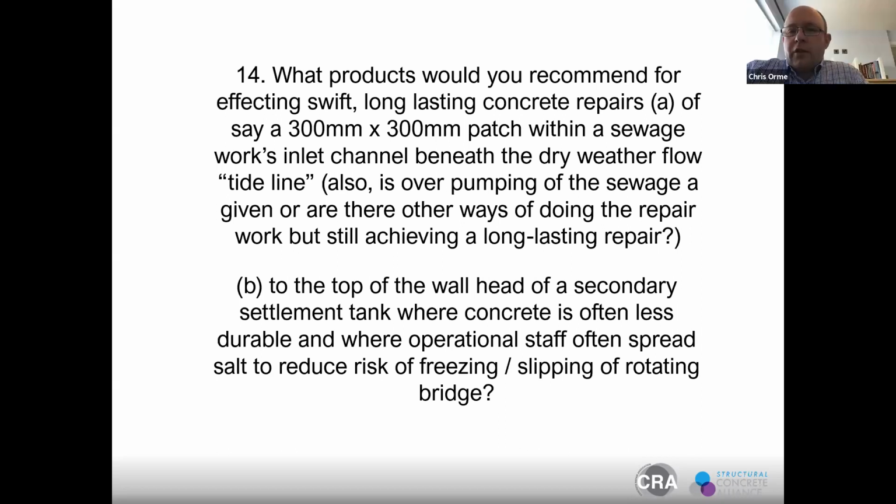The other thing to consider is speed of installation. Sometimes these warehouse environments are very highly trafficked, and they need to get on the floors very quickly. So it could well be that you could look at using some fast set repair materials, and indeed joint sealants and things like that later on, if that's what you need to do as well.